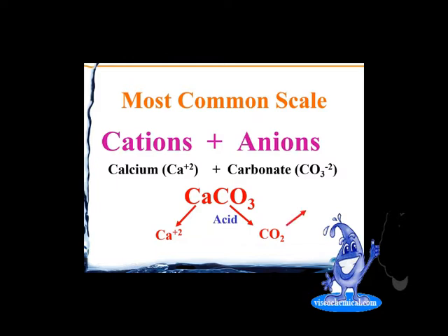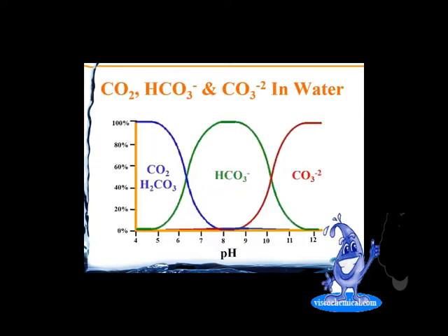But that's going to be the only easy one. And again, it's this relationship between CO2 below a pH of about 5. All of your CO2 is in dissolved CO2 form, which you can call carbonic acid. Well, as the pH goes up, when it gets to the neutral range, here's where most of our natural waters are. The pH has converted most of the CO2 into bicarbonate ion, but that's a single charged ion. That's not a problem for us.